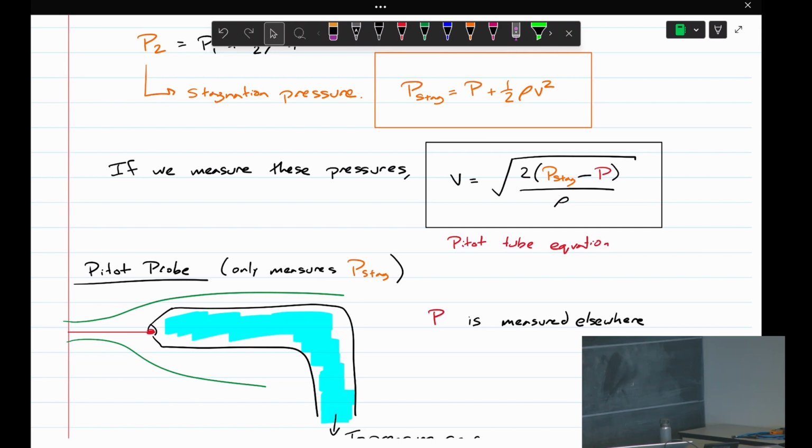Yeah, you have to be careful. So for certain devices, mechanically, it's a very good question. If your tube is designed with the right diameter, you might actually cause resonance in your tube and it might bend. So it also has to be able to withstand the actual aerodynamic forces placed on it.